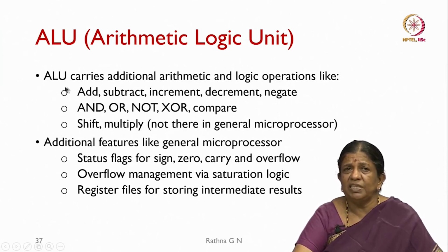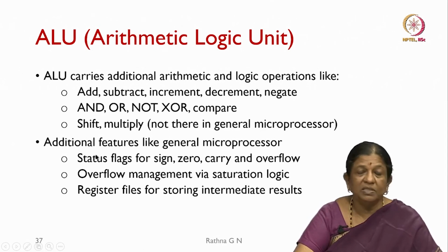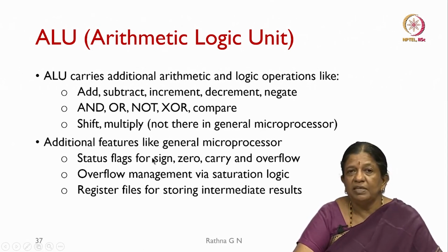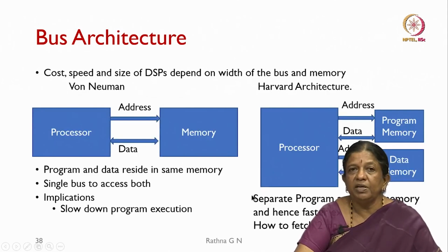Apart from addition, it has to take care of increment, decrement, negate or other operations, and then shift, multiply, and additional features like in other processors. We should have status flags for sign, zero, carry or overflow, and overflow management via saturation logic can be incorporated, and register files for storing the intermediate results.